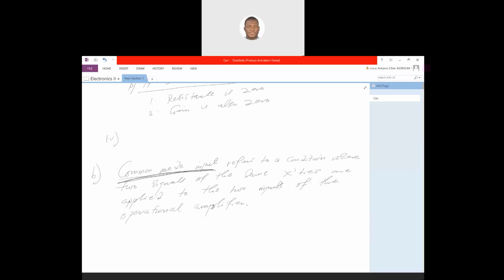An operational amplifier has an open loop differential gain of 120,000 and a common mode gain of 0.5. Determine the common mode rejection ratio and express it in decibels. So it is basically similar to what we did in example 3 or tutorial 3. Okay? Are we all clear? Yes.